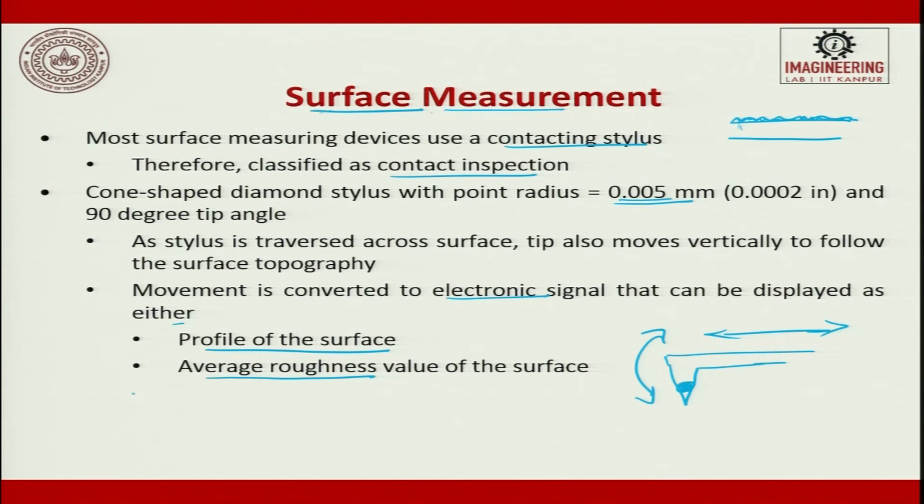roughness. So, if you are working on the electrical field, we also look at RMS values, or we try to look at peak to valley height. These are some of the parameters which are used to measure the surface.